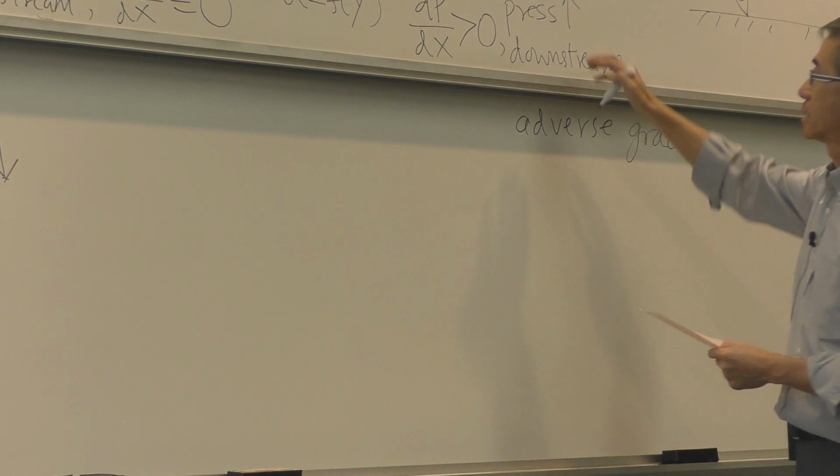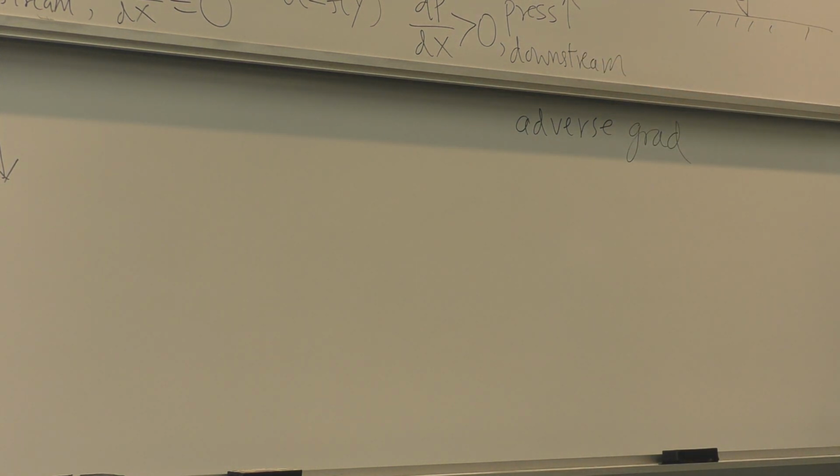So these cases of increasing pressure downstream is what we call adverse gradient. Anytime you see a pressure increasing in a device, as you march downstream, you have to be on alert because it can bite you. So namely, two devices for engine application that you see that, where pressure at the exit is higher than the inlet.